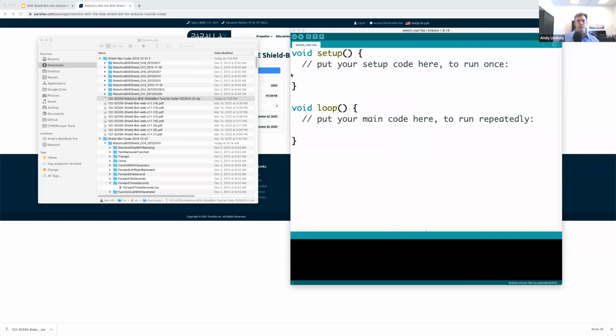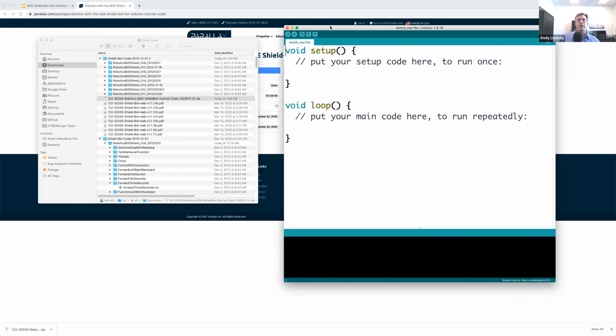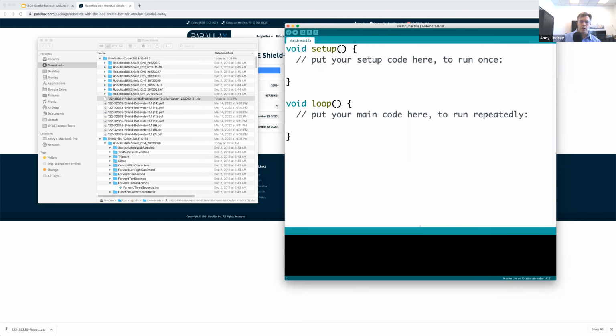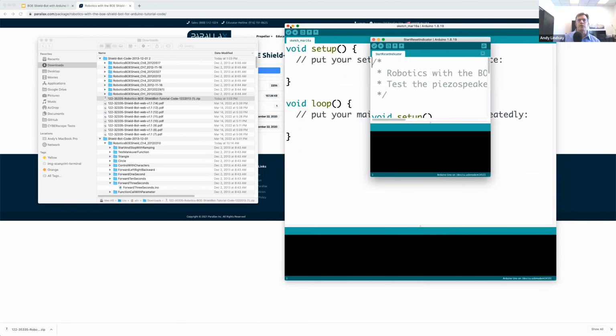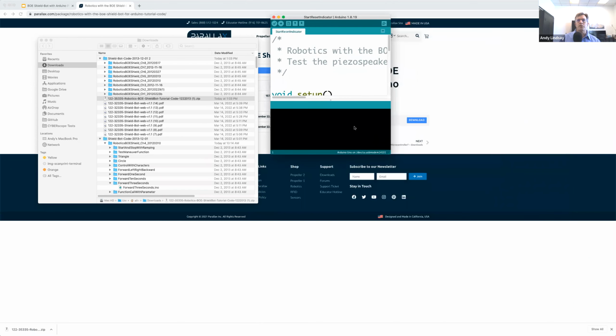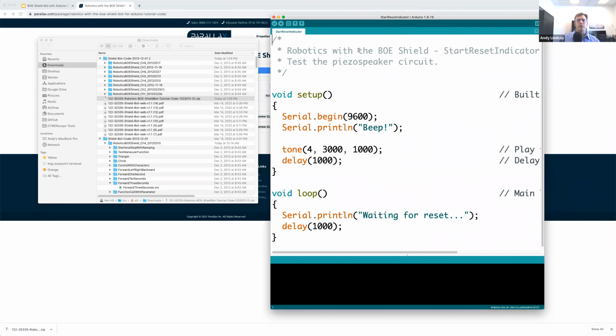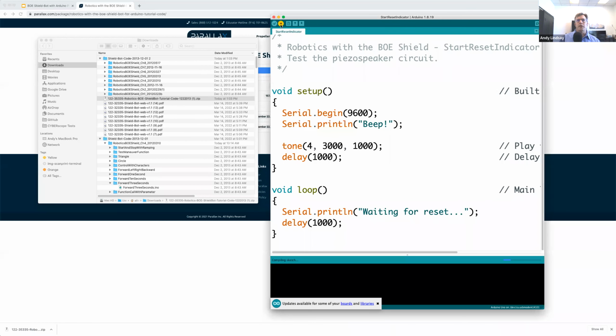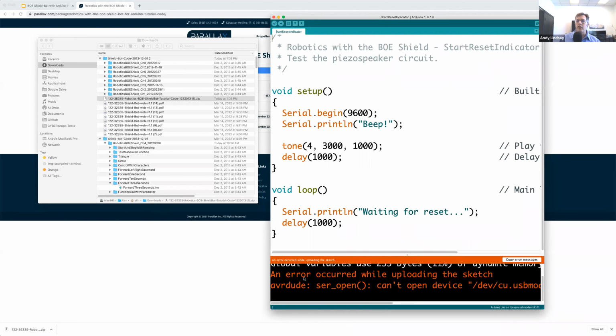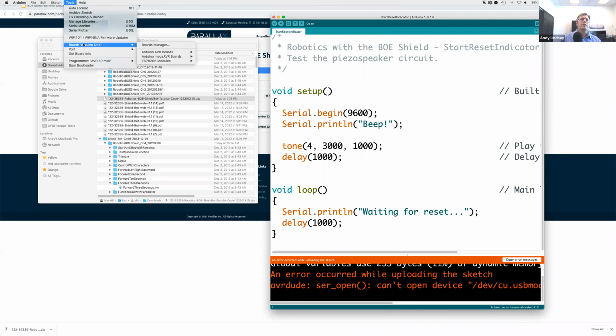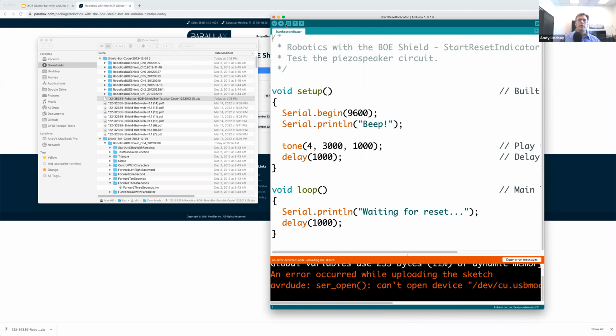I want to make sure that everybody can open it with their particular IDE. So I'm going to show you how that works. Now, in the IDE, it opens in another window. And then we'll also look at the Arduino web editor and Codebender in terms of opening the files. So here we are with the file, and we'll go ahead and run it. Hopefully I'm still connected. Compiling sketch, so it shows me the status down here. An error occurred, which probably means that I don't have the right port selected. There's the Arduino Uno. Then try again.